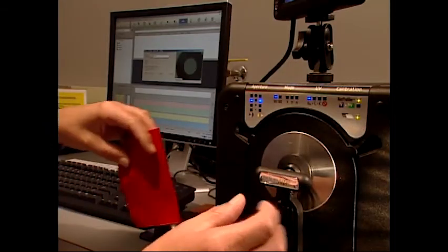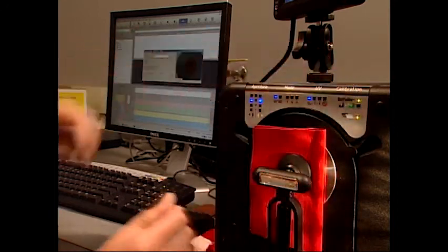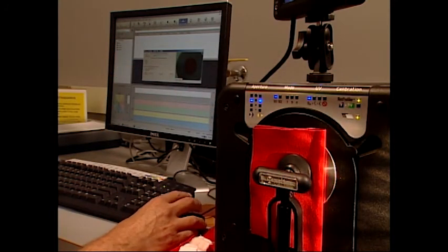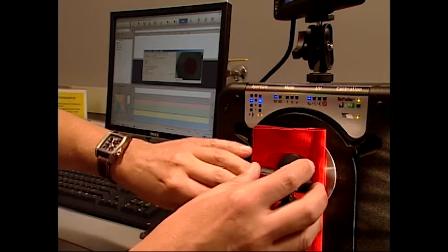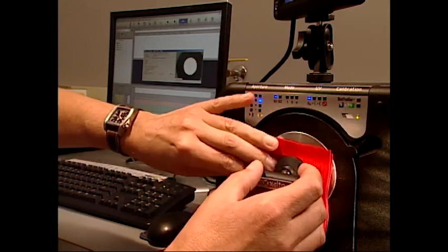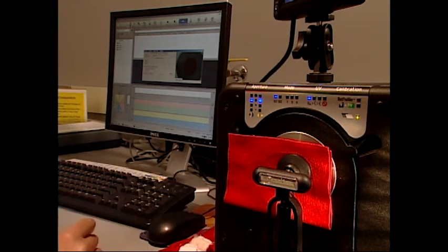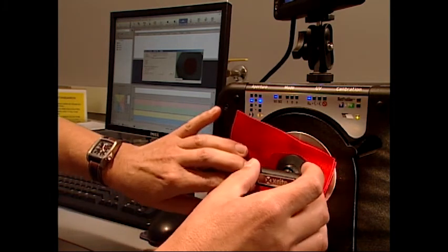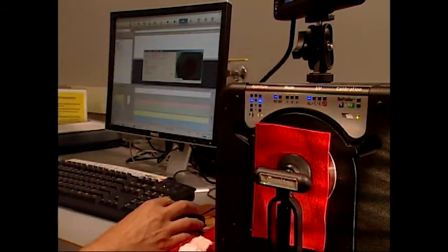Instrumental assessment of color change can be attained by using AATCC Evaluation Procedure 7, Instrumental Assessment of the Change of Color of a Test Specimen. This evaluation can be used instead of Procedure 1, Grayscale for color change. Procedure 7 is effective as a rating tool unless the specimen tested possesses optical brightening or fluorescent whitening agents. A spectrophotometer is used. Calculations of color difference are mathematically expressed as a grayscale value.